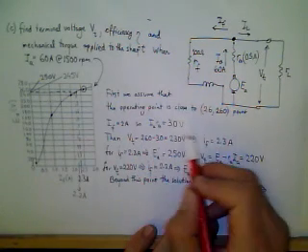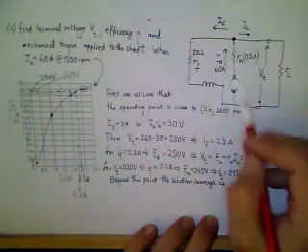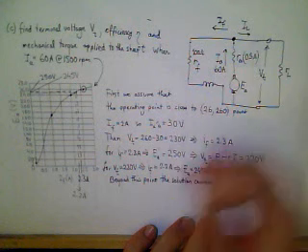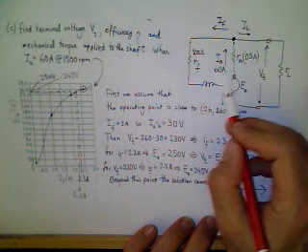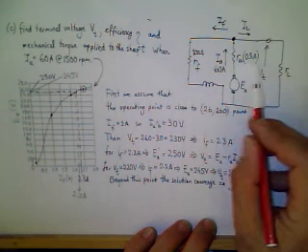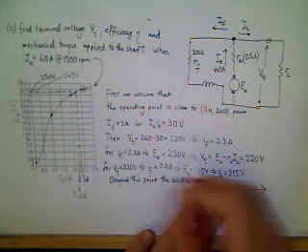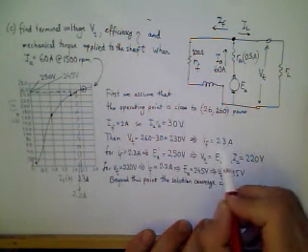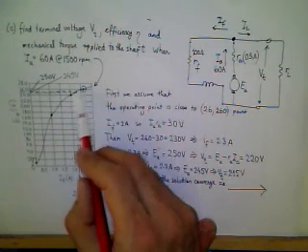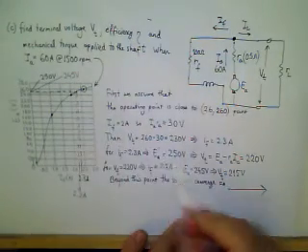First, we assume that the operating point is close to 2.6 amps and 260 volts induced voltage point. If IF is 2 amperes, IA RA is around 30 volts, because there is a 30 volt voltage drop across RA. RA is considerably large. Actually we make a little error here. IF is found to be 3.3 amps, 2.3 amps, sorry. For field current 2.3 amps, the induced voltage is around 250 volts, roughly with graphical errors.